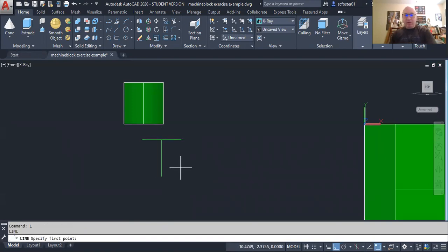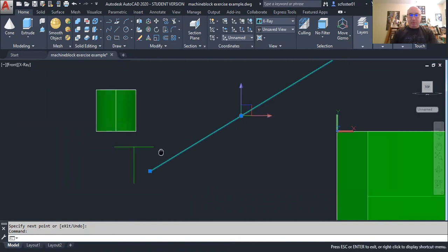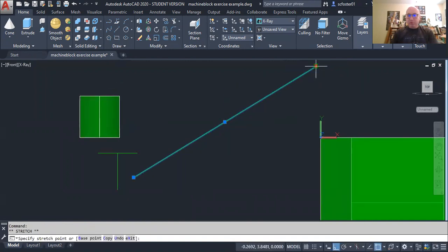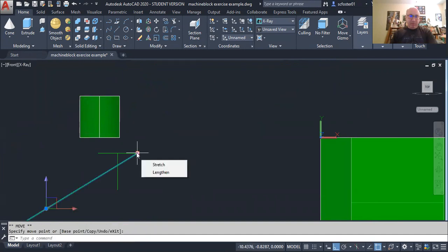Now I'm going to draw a line to some random point in space, at, let's say 12 inches. Remember, to draw an angle, you type in the less than symbol, 30 degrees. So it didn't need to be that big. So I'm just going to click on the grip and drag it down until it snaps there.